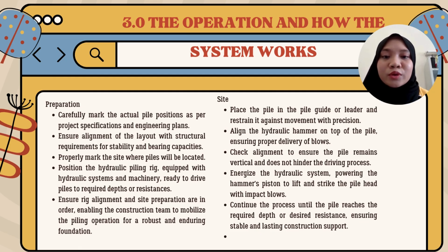Hi, Assalamualaikum. I'm Nurul Syazwani binti Abdul Hamid, and we talk about the operation and how the system works. So for the preparation, the contractor marks the actual pile position as per project specification and engineer plan, and it will assure alignment of the layout with structural requirements for stability and bearing capacity.